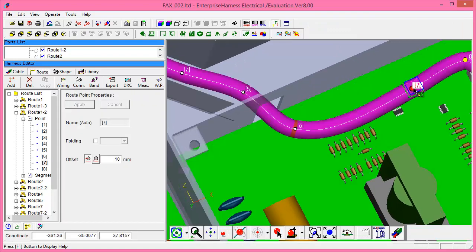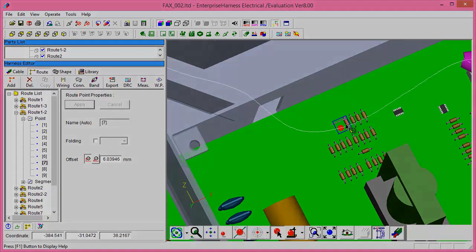Editing the route such that errors are removed will eliminate the places that are bending more than the specified radius of curvature. In this manner, you can modify the route so that it has the correct bending.